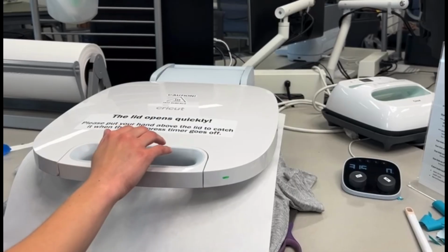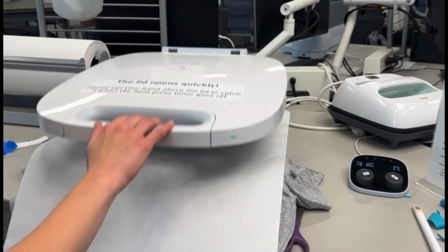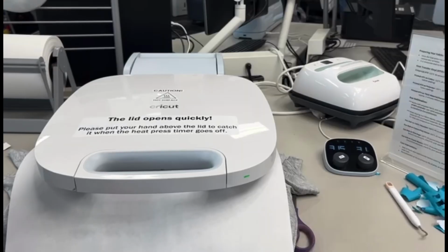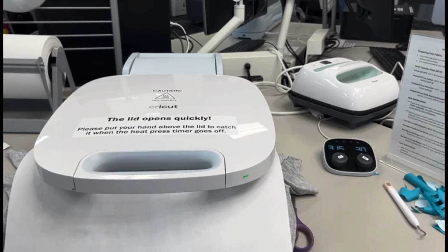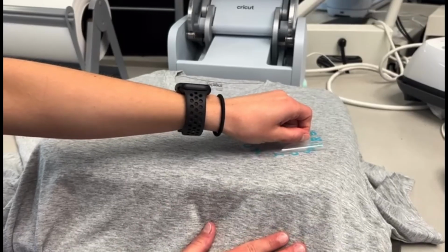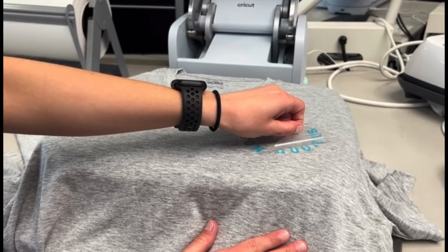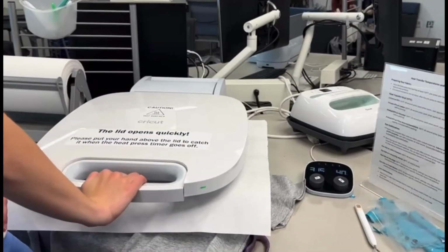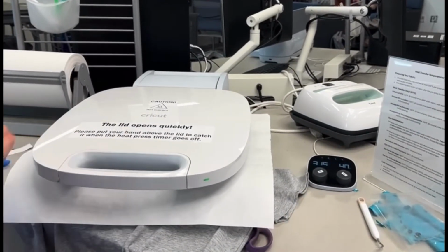Polyester is a thermoplastic that can melt or warp if heated too high, just the same way that heat transfer vinyl does. Because of its long chain-like structure, too much heat can cause the molecules to gain energy and disrupt the structure of the polymer. In our case, we wanted the vinyl to melt and warp, but not the shirt. The structure of the vinyl was created in such a way that it would soften at lower temperatures than the material it was being applied to.